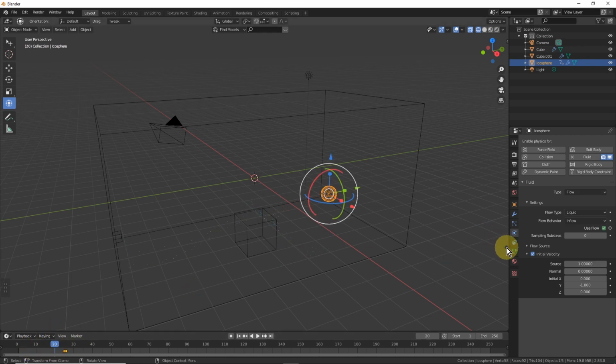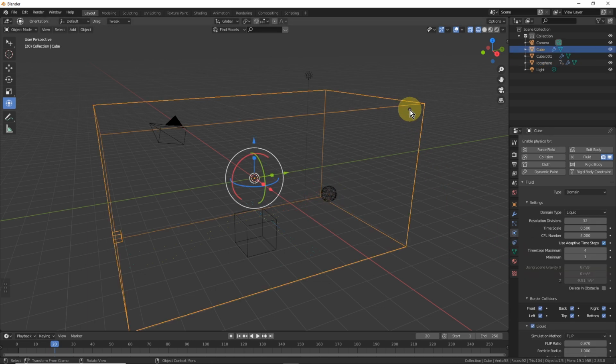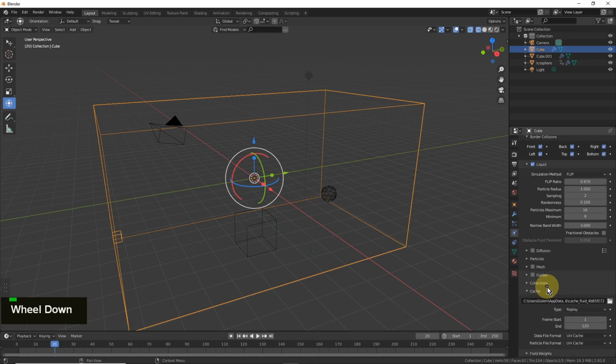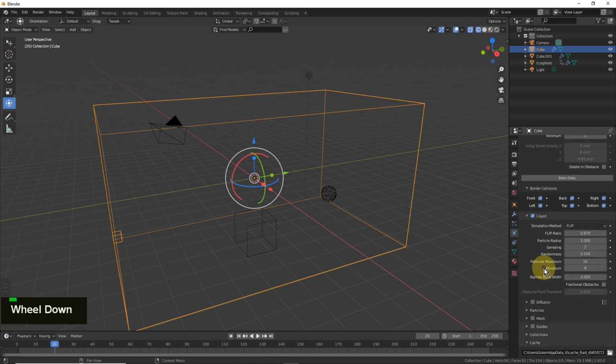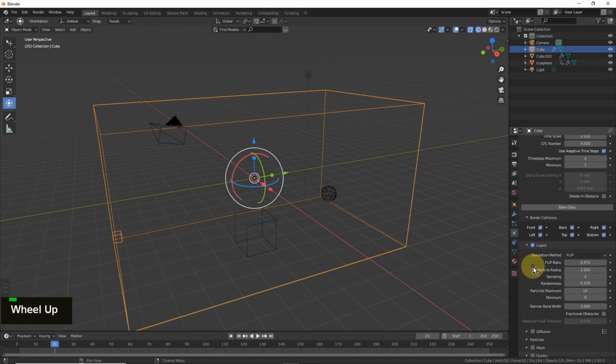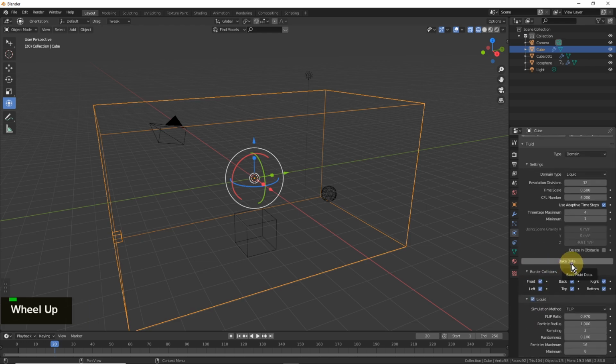Now if you go back, choose the domain, and now we can try to really test this one. And there are two options for that. It's modular or it's final. Modular opens up this tab here, and it says bake data. So this would bake the particles, but not the mesh. So we don't have selected the mesh yet, but we can start the particle simulation.